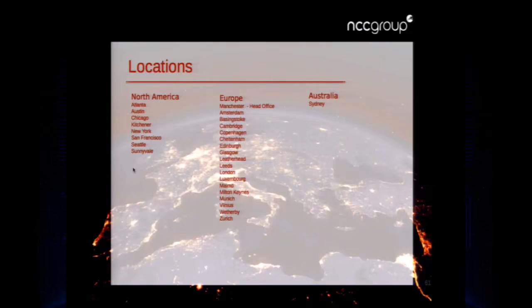Any other questions? If you're taking out all the decoupling caps in a full-blown system, I would think that would be dangerous. Yeah, it's pretty dangerous. You want to take them out around the thing you're targeting, though. That's the general idea. You definitely don't want to take out the decoupling caps near the crystal if you're just doing a brownout attack. But any of the power decoupling caps near the thing you're targeting, you should try to take those out. But you want to do that slowly.